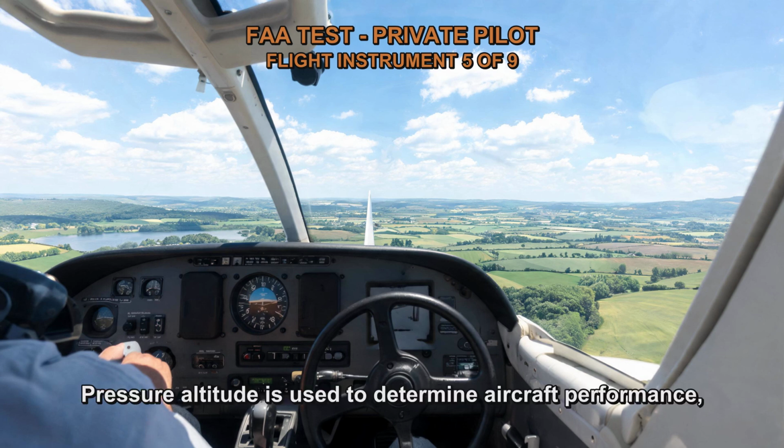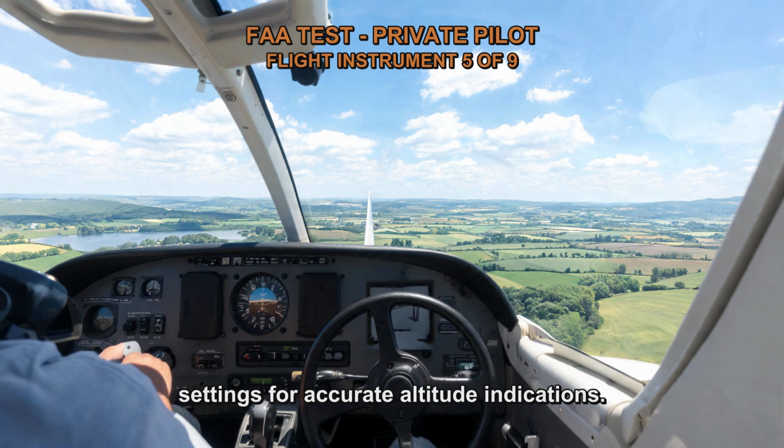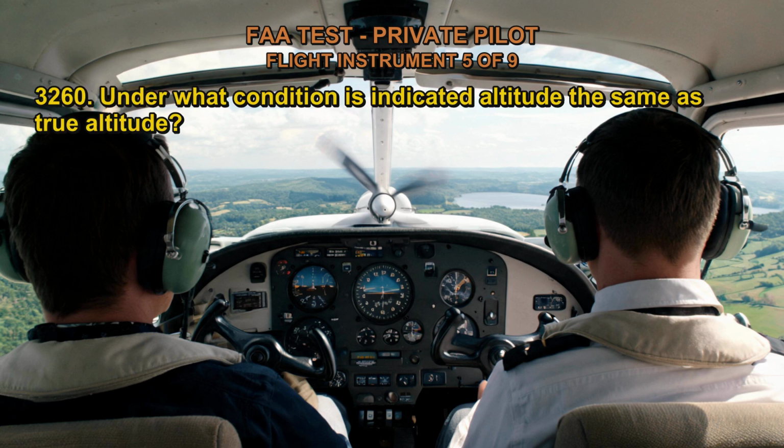Pressure altitude is used to determine aircraft performance, aircraft separation in airspace, and to establish altimeter settings for accurate altitude indications. It is not affected by variations in atmospheric pressure caused by weather conditions.